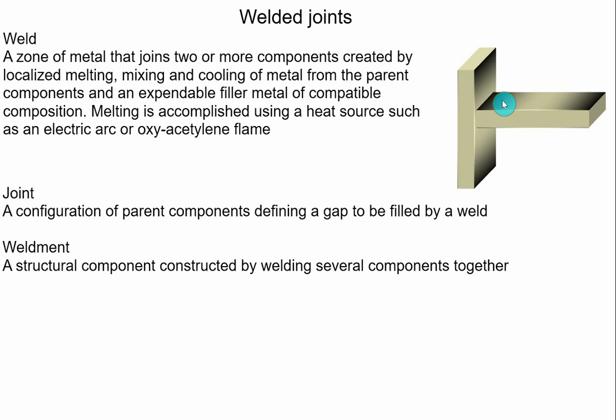So we have two metal plates here and we wish to make a joint. For this purpose, these two plates are first cleaned and then the welding is done on this corner as well as this corner. So the welding is done in this fashion. Depending upon the force required, we have to do the welding. We are interested here in the size of the leg. This one is called the leg, which is represented by H. This one is also leg size equal to H, and L is the length of the weld.